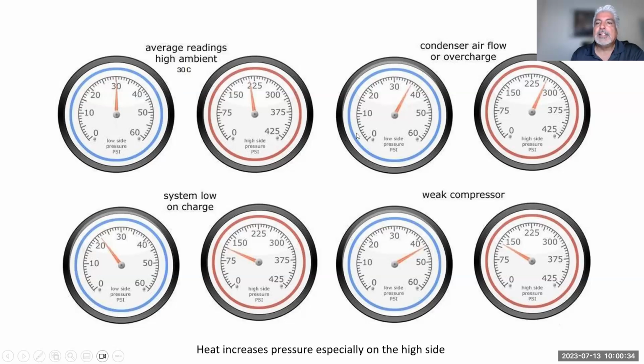All right. Now, what about condenser airflow or overcharge? That question's asked. Yes, this is actually, believe it or not, normal for our area. Like you saw in the previous diagram. Why? Because our ambient temperatures are very hot. Like yesterday, it was hot. So we saw 250 on the recording that I showed you. And here you could see again that we were running around 38.